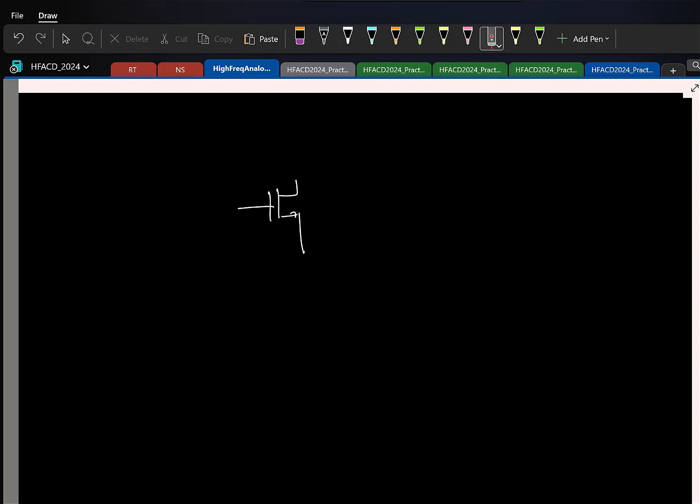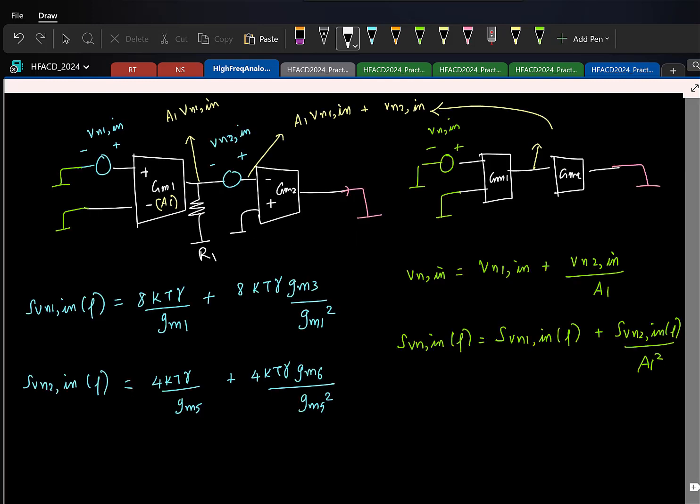The noise is coming, if you go to the physics, because we have random thermal motions of the electrons. That is modeled in the current directly. The ro is our way of modeling channel length modulation. It's not a physical resistor that is present in the transistor. So that is why we don't have to worry about it. But if you go ahead and put an explicit resistor here, then you have to take into account the noise of that resistor.